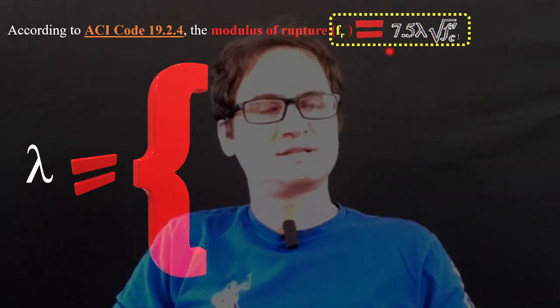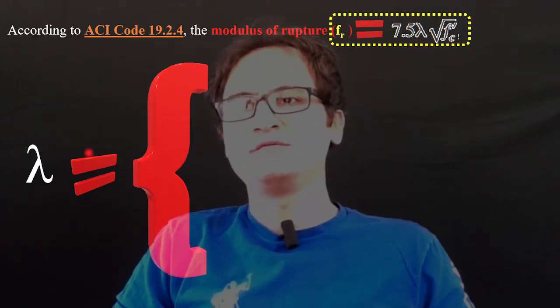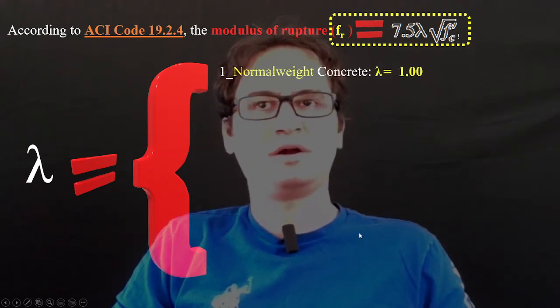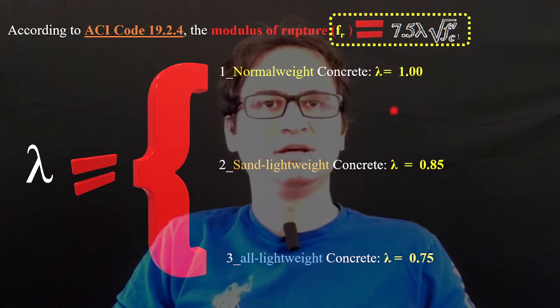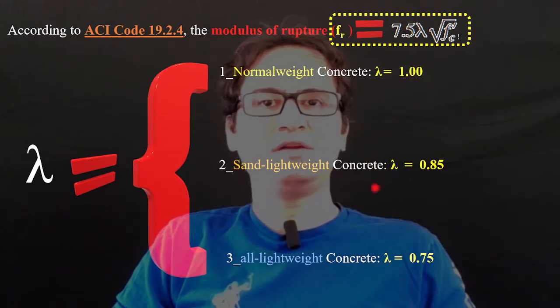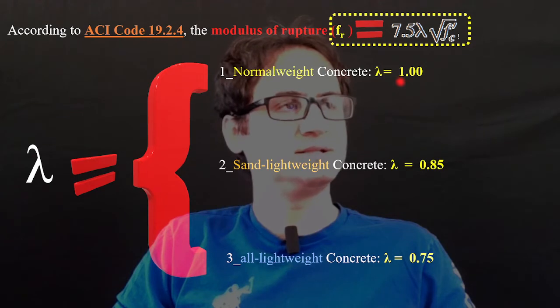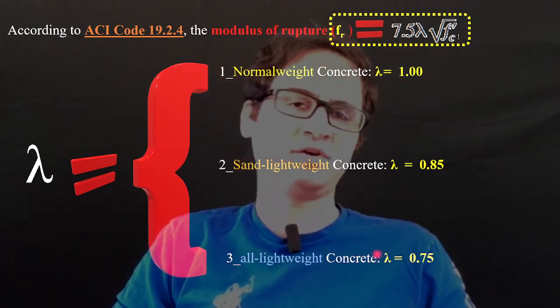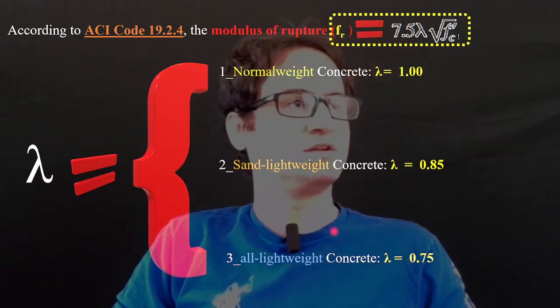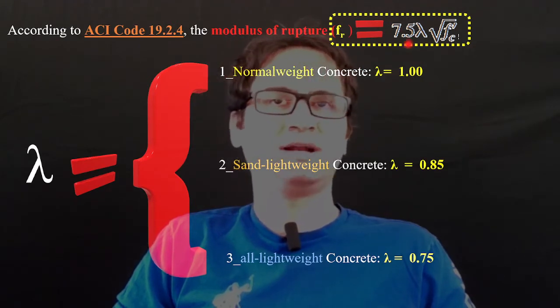And the formula is 7.5 times lambda times square root of F prime C, in which lambda goes by three categories. The first one is normal weight concrete, in that case lambda is equal to 1. Sand lightweight concrete lambda is 0.85. You can see easily the reduction pattern of lambda, and also all lightweight concrete, which lambda is 0.75, and it just replaced in the modulus of rupture to calculate Fr.